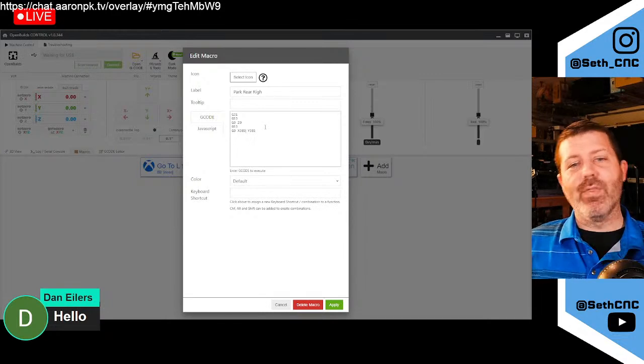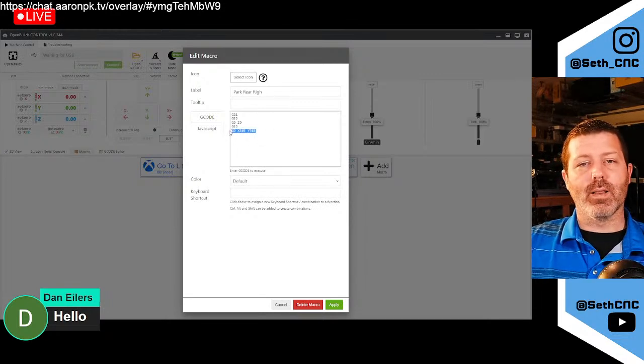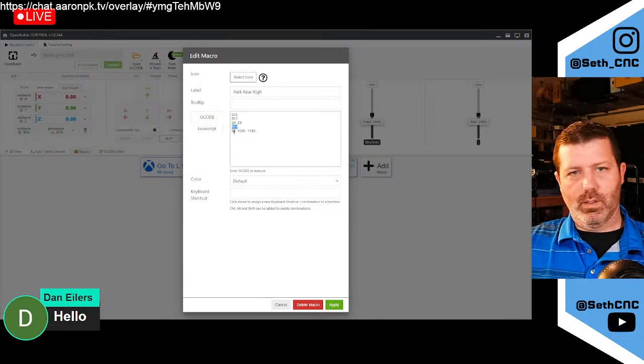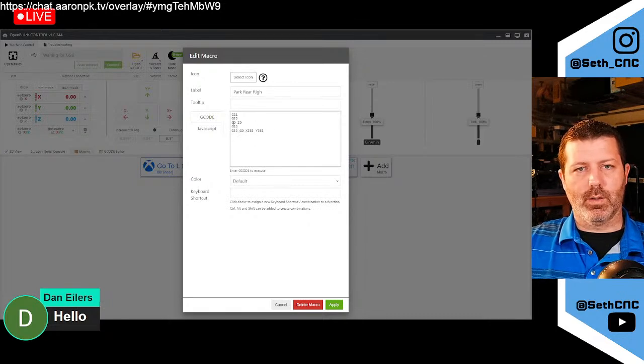It's not going to go back and then to the right, because this is all on one line. It performs this at one time, right? So because we're using G53 here, that puts it into, oh, and those are supposed to be on a single line together. That was an issue with the way the person wrote this up in the forum post, is that these need to be on a line together like that if we're going to use absolute coordinates.